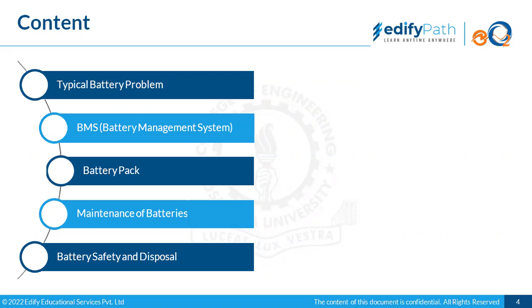When we assemble the battery, we have cells in standard sizes only, so our dimensions, everything, will depend upon them. So we should at least be aware of the quality of the cells and the data sheet of the cell, so we know what the output would be and how the battery would behave. Quality control won't be an issue if we are aware of the cell data sheet.